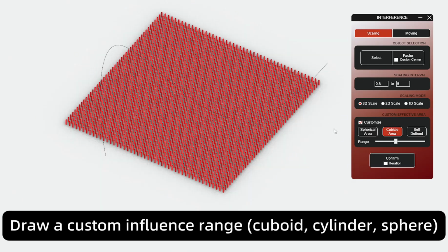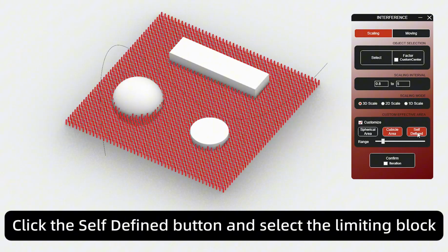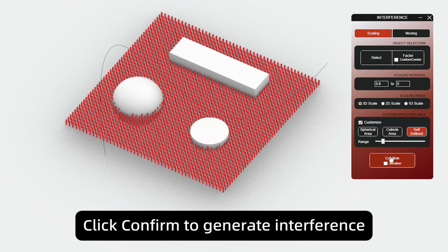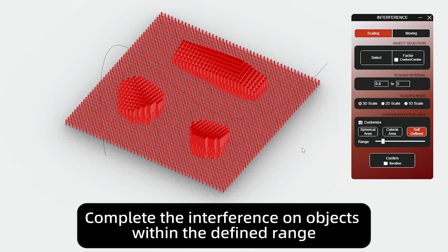Draw a custom influence range: cuboid, cylinder, or sphere. Click the self-defined button and select a limiting block. Click Confirm to generate interference. Complete the interference on objects within the defined range.